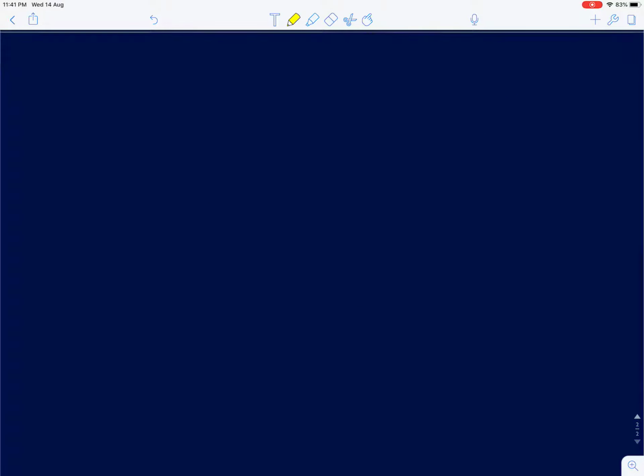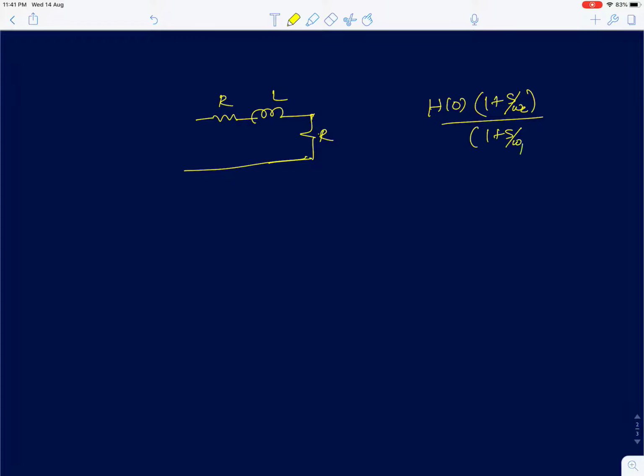So I'll now start analyzing, we'll start deriving transfer functions and draw the frequency response for different first order RL networks. So we already discussed how to derive transfer functions for first order RC circuits. All you need to do is find out the DC gain, and this is valid for transfer functions which has a finite 0 and a pole. So you just need to find the pole and 0 and the DC gain. If you know all the three quantities, then you know the frequency response completely.